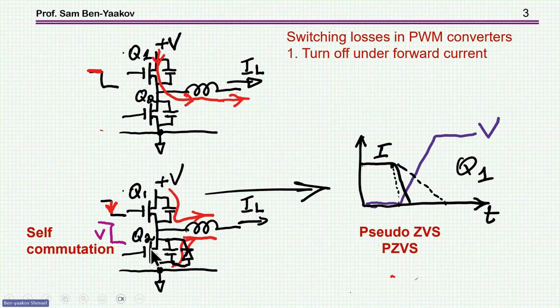And the voltage itself is changing because we are charging or discharging, as I've said, these capacitors through this current. Depending on the magnitude of the current and the size of the capacitance, we'll have here a slope. If the capacitance is large, then it'll be slow. And if the capacitance is small, it'll be fast. And then depending on the current.